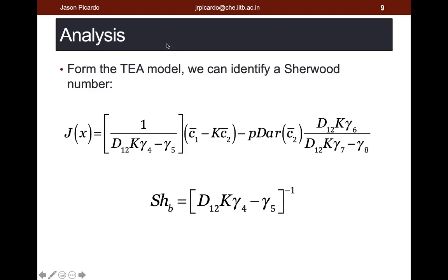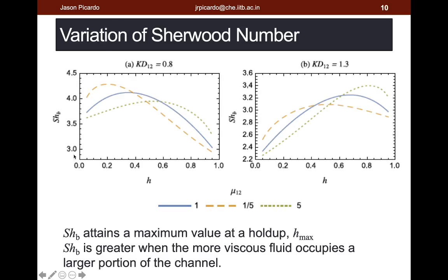Okay, another thing. Ignore this TAE model, that's just a name I gave it. But the average model lets you, like I said, without the reaction, write the mass transfer as a driving force times a coefficient. So in non-dimensional terms, this is my Sherwood number. So I obtain a Sherwood number for this specific flow analytically without doing experiments. And because I have it analytically from my average model, I can look at how the Sherwood number, or the non-dimensional mass transfer coefficient, varies with various parameters.